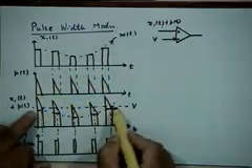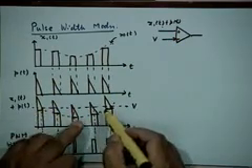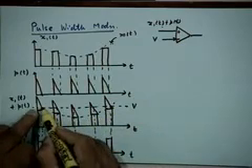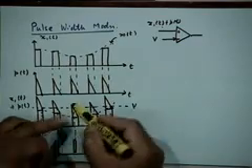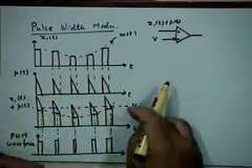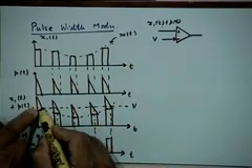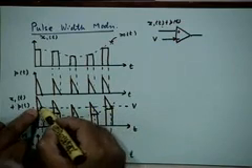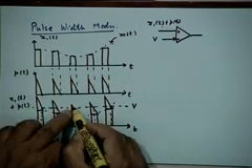The point of intersection of this constant voltage line with this added waveform would generate different durations during which the sum amplitude is larger than the reference. Here it is larger than the value V for a much larger time than here, and so on and so forth, right?